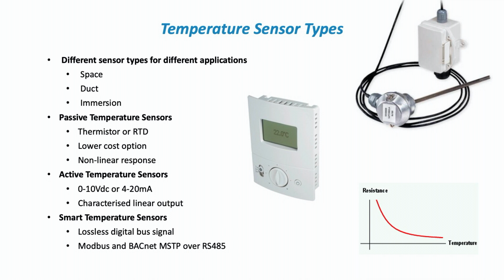For temperature sensors, I've actually put in a couple of temperature sensor types. I haven't done this for every application because there's lots of different types of temperature sensors out there. The first thing you have to do when you're selecting a temperature sensor is obviously choose the correct application: space, duct, and immersion. And of those duct and immersion sensors, you need to be acutely aware that whilst they can often look the same on the outside, they are not always the same on the inside.